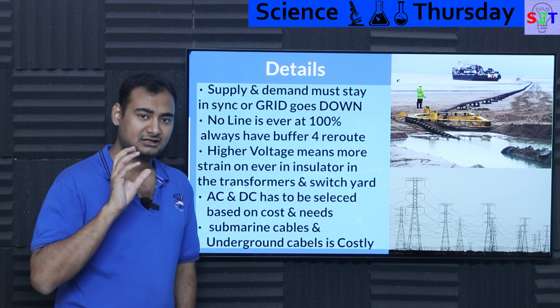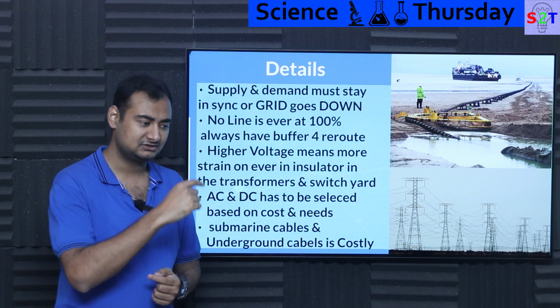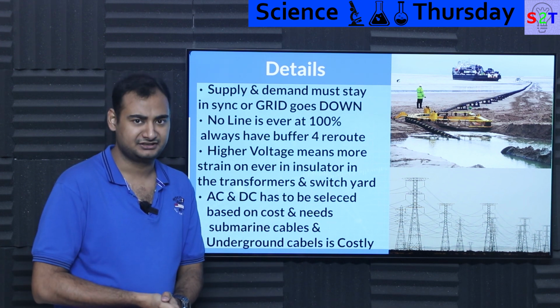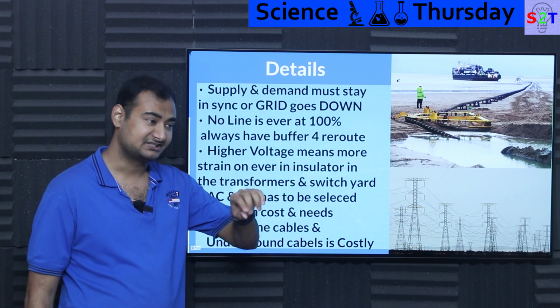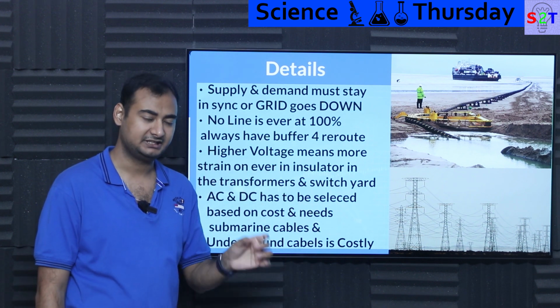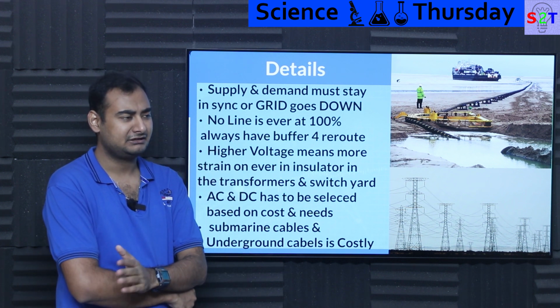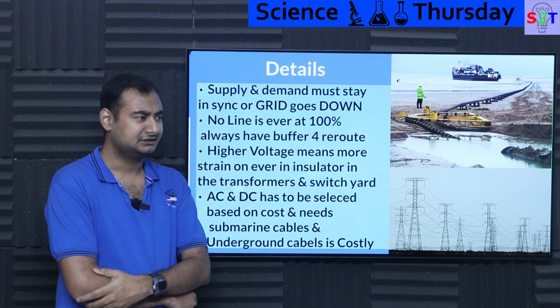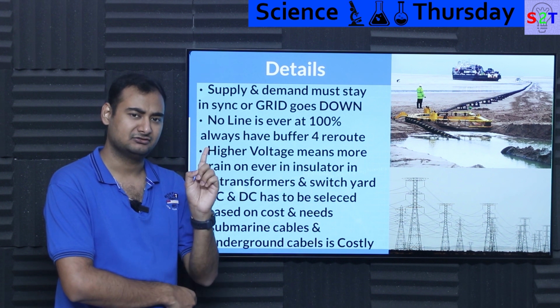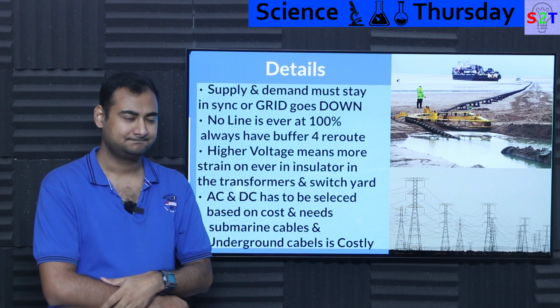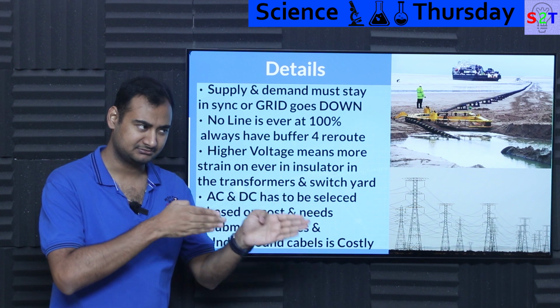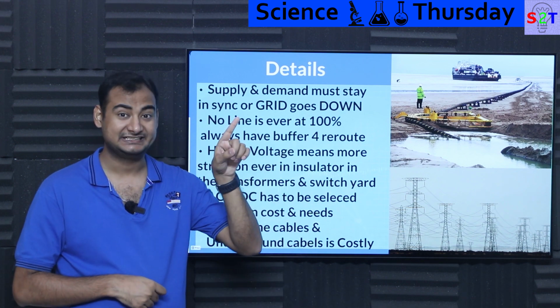What will happen? Now there are sensors on the generator shaft that are looking at the RPM. Let's say the RPM is 1500 RPM. And that RPM directly corresponds to the hertz in the grid, as in 50 hertz, 60 hertz. Now, when they are looking at the hertz, everything is fine, everything is tight. And then they're like, wait a minute, why the heck did the hertz go down from 50 to 49.99? Okay, the computer would now be alert. Okay, something's off. Then it goes to 49.8.